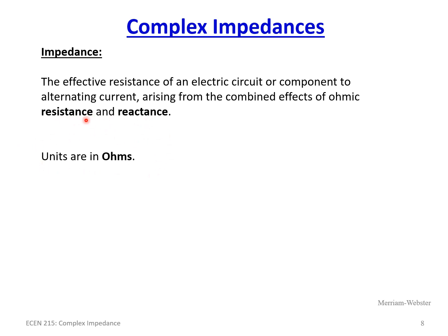So all we've introduced is this thing called reactance, which is the imaginary component of the impedance. We still have a real resistance, but now we've added this imaginary value called the reactance. In the case of the inductor, as we just saw, there was no real component. It was all imaginary, so all of its value was in reactance. The units are still considered in ohms. This is why it is critical that you master the phasors coming into this section, and especially in the upcoming section where we're going to actually use complex impedances in circuit analysis.